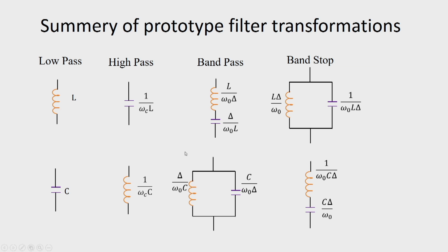So, we can calculate the component values of these transform circuits, and therefore, when in the prototype we will have to substitute them by respective combination of elements. We have only done the frequency transformation. The impedance scaling also needs to be done for transforming the source impedance. Impedance scaling also need to be done to complete the procedure.